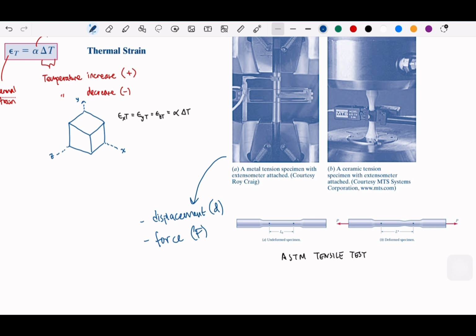This testing is done with the assumption that they are going to take this as slowly as possible. So the rate should be slow. Why? Because we want the specimen displacement to be as small as possible at every increment of time.